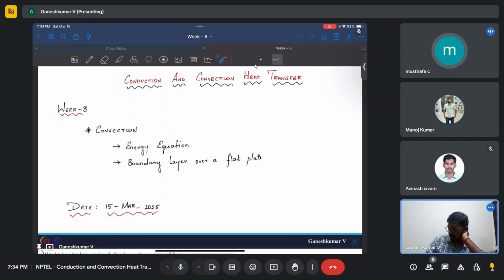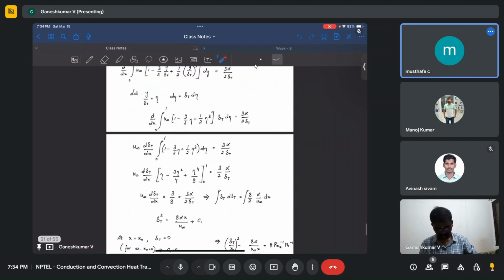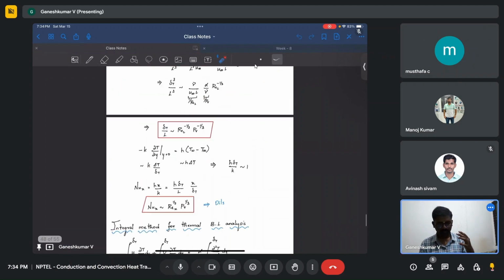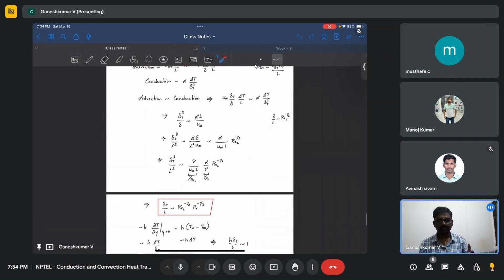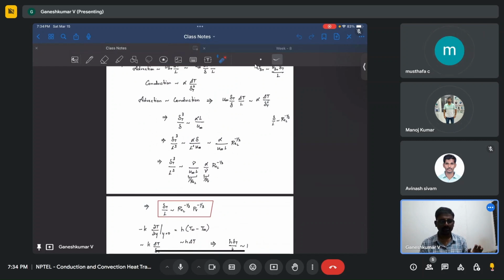So there are only 2 kinds of work. One is because of surface forces, and one is because of body forces. Now, you have to think, what is this surface force? Is the surface force occurring because of a flow? If it is yes, then it becomes a flow work.